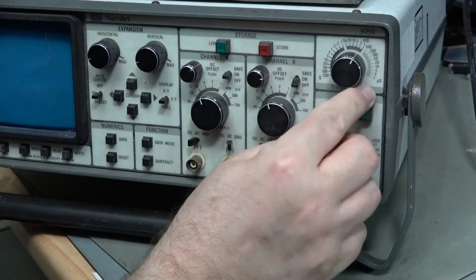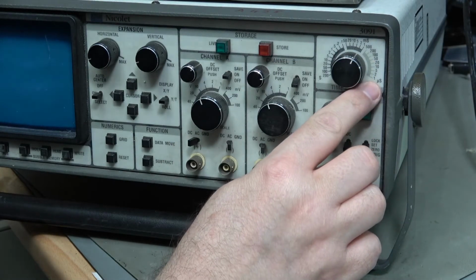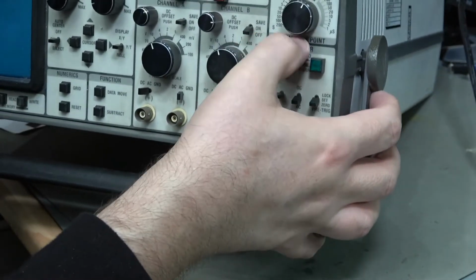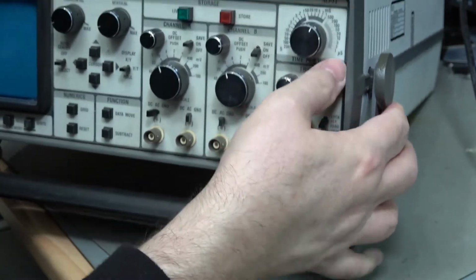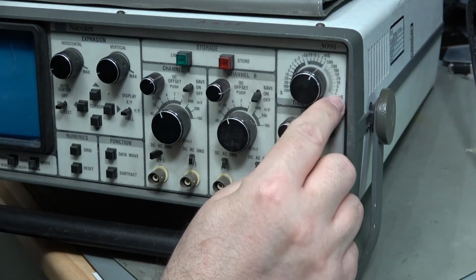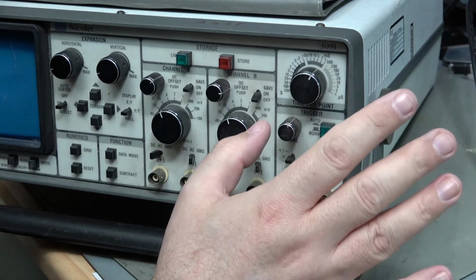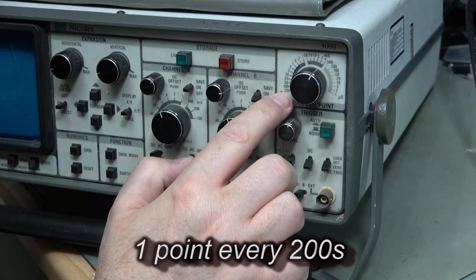But let's take a look at the time base over here. So here's the time base. The fastest thing on the time base is 1 microsecond. The important thing to realize is that this doesn't say time per division. This is time per point, because this is a digital storage solution, and the fastest it can do is 1 million points per second, which isn't very many, of course. Over here is 1 point every 2 seconds.